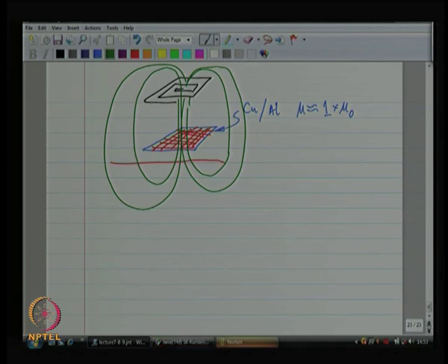What is going to happen now is that you have probably created a lot of plates in between for the parasitic capacitance. So, earlier the parasitic capacitance was the capacitance between the inductor and a ground plane, you know, your substrate, inductor and substrate, these are the 2 plates.